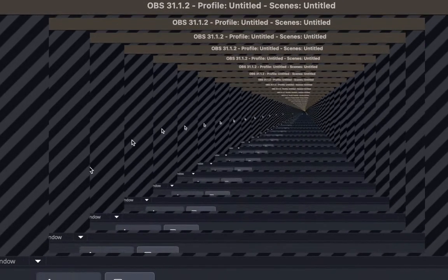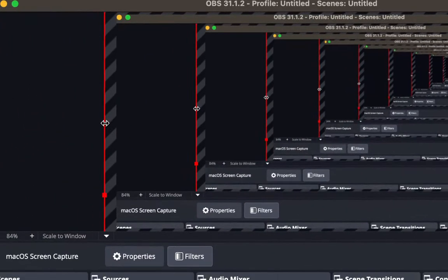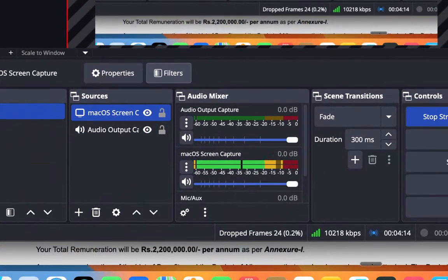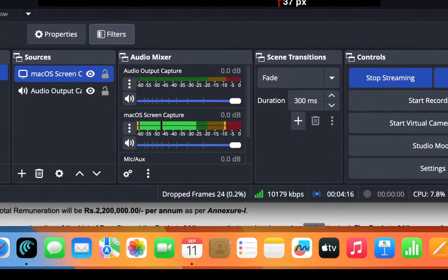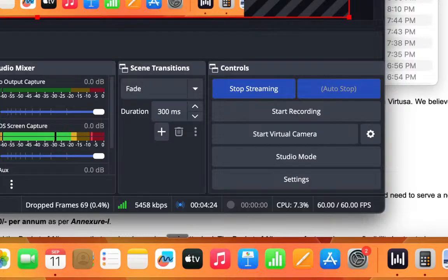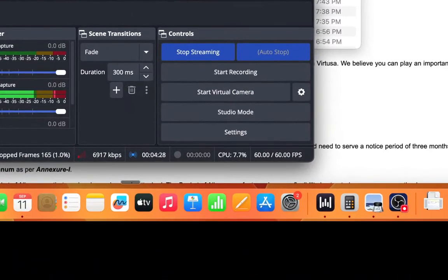It will improve the yield rate. Yield means, if on the wafer we have 100 chips, how many are properly working and how many are defective. If more chips are good, that means the yield rate is good. And defect density is how many of them are going defective. Using it in fabrication, we can reduce the number of defects and improve the yield.